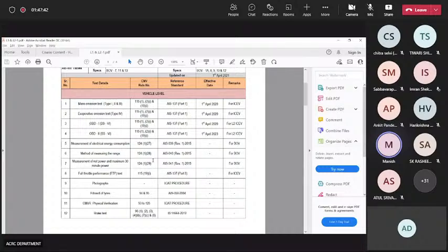All these tests are done on the vehicle level. So the vehicle has to have the charger, battery pack, complete vehicle, all the accessories, everything has to be there. It will be submitted to agencies, ARAI, ICAT, and they will check your vehicle capacity. Then they will check the range, the method of measuring the range.